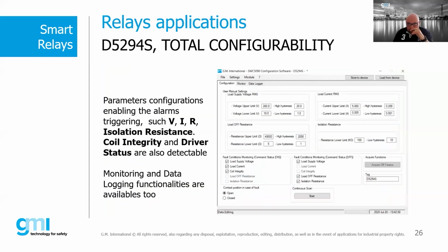In the next slide, we can see that the D5294 is totally configurable. This kind of smart relay can be configured in case the parameters that shall be monitored are specific and the acquisition of the fault cannot be achieved with a standard monitor relay.